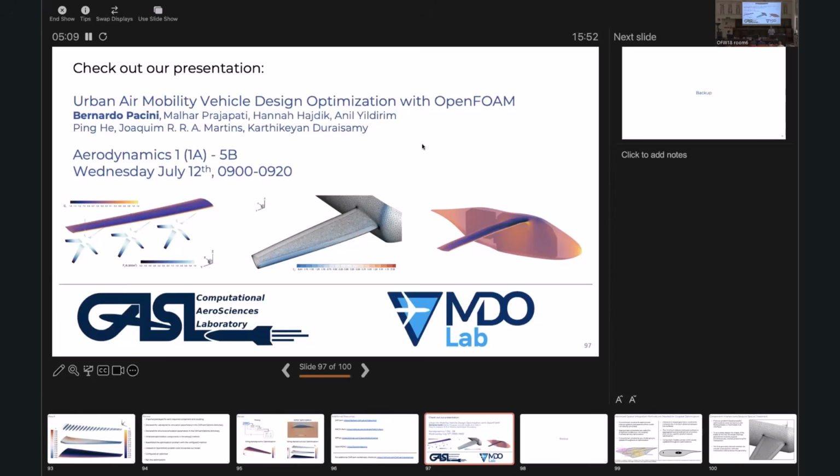If you're particularly stringent about mesh quality, then you could run DAFoam for some iterations. It might run up against the wall for that mesh quality. You can remesh and then run some more steps. For my case in particular, I see some significant changes in the mesh geometry, but I haven't seen particularly bad degradation of the quality. So I personally haven't had to do that. But no, I do not directly control the quality of the mesh.